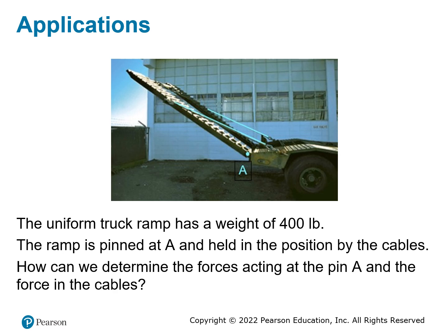This ramp here has a weight, so if you want to draw a free body diagram of this ramp, then you certainly need to consider the weight of the ramp. What else do we need to consider? Well, certainly there are the cable and the pin, and they all will create some reaction forces when you isolate the ramp.